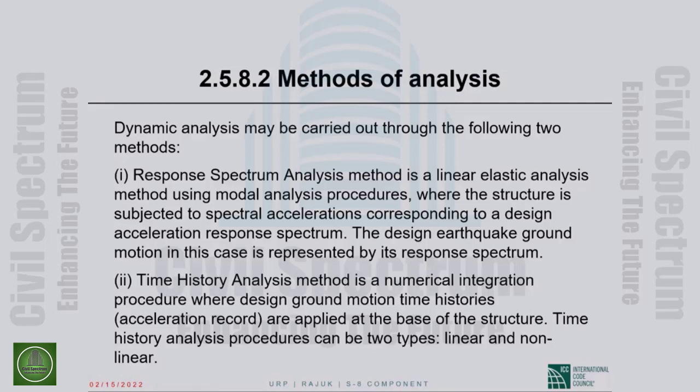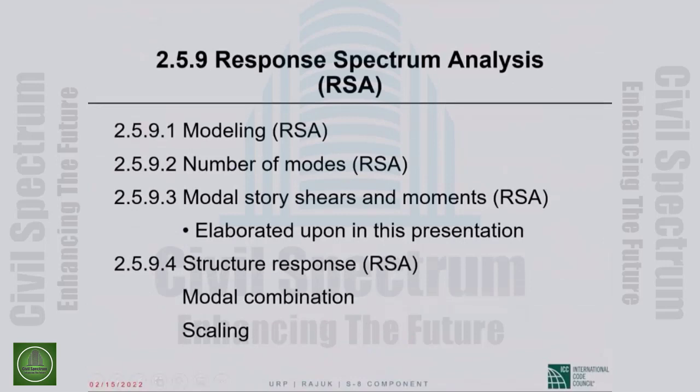In the US, I think things are changing rather rapidly in favor of response history analysis. In section 2.5.9, BNBC tells you about a number of things related to modal response spectrum analysis. First, modeling, then the number of modes that you have to consider. Then modal story shears and moments is the subsection title within parenthesis, response spectrum analysis.